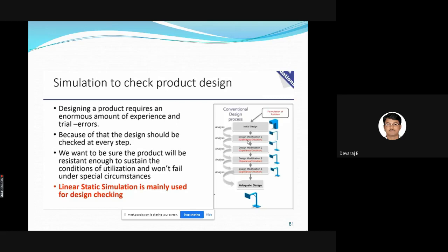So if the stress reaches 90 megapascal inside the material, in the industry they will tell you the material will fail. That is what they follow in the industry. So if the stress produced inside the material is only 0.04 megapascal, the material can withstand up to 90 megapascal, right? According to the industry right now. Yes, sir. If its yield is 270 and its FOS is 3, then 90, sir. Yes, 90 megapascal. But when we do the analysis, it is only around 0.04 megapascal, right?